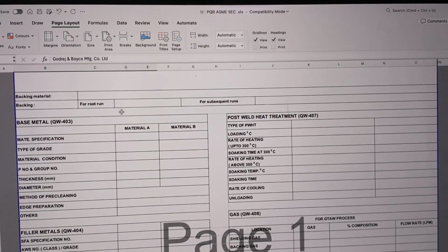It will improve corrosion properties, and sometimes we get good impact properties also, because there is no sensitization, so the impact properties don't deteriorate, and we get a good impact in stainless steel up to -196 degrees Celsius.